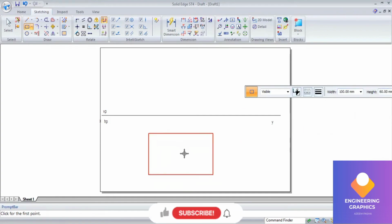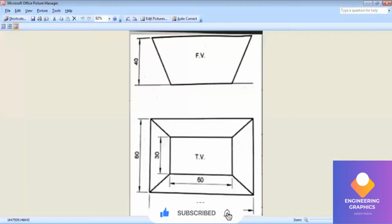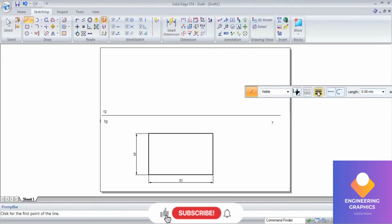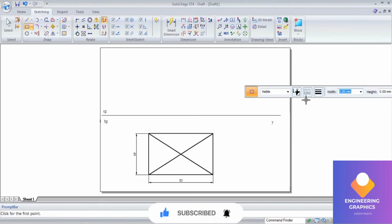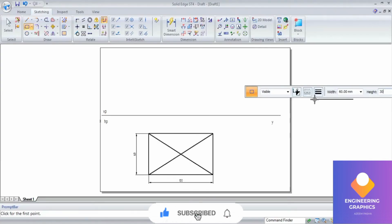Now another rectangle we have to place centrally, that is 60 into 30. In order to place it centrally, first we'll draw the diagonals here so that it will be convenient for us to get the center point, so we can place it properly at the center. Again I will go to rectangle by center, giving width and height 60 into 30. Okay, place it centrally.